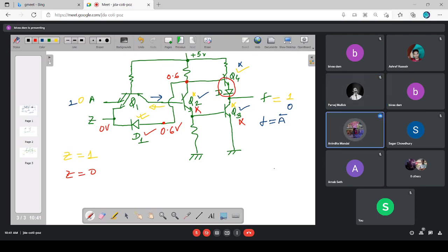No, sir. So this will also be off. From this particular terminal to this side, how much impedance are you getting? Infinite. On this side, how much impedance? Infinite. So this output node is placing infinite impedance to the external world.